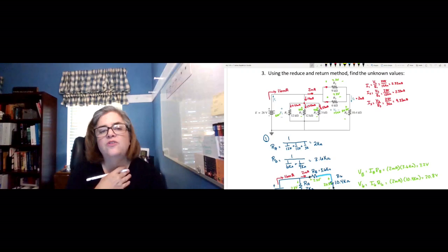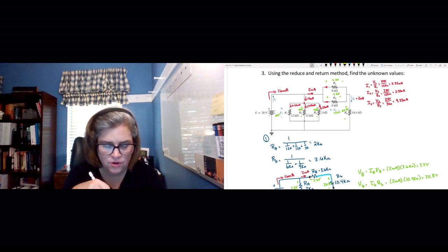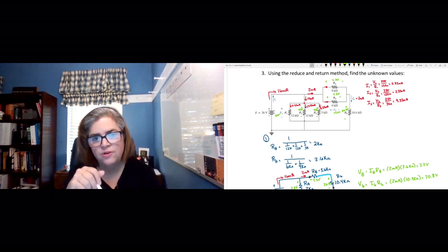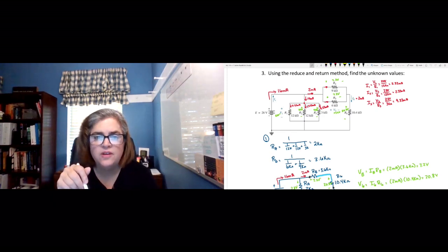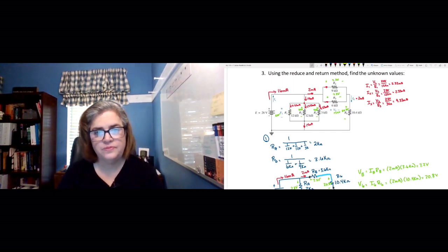And again, do your little calculation coming in. We've got 14 milliamps coming into a current divider, 2 1/3 through R1, 2 1/3 through R2, so that's 4 2/3, and then plus the 9 1/3 going through R3, so that's 4, 5 plus 9 is 14, and then that'll be 14 again on the other side.